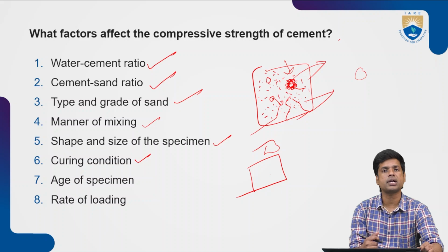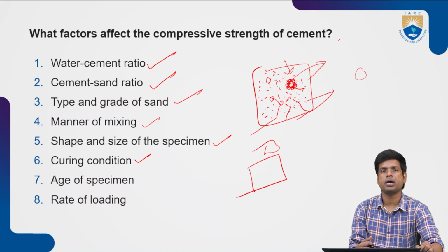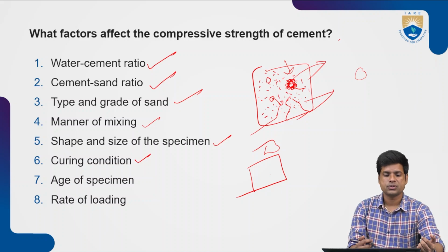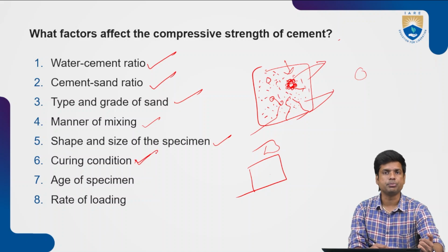Suppose the curing is not done, and the water application is missed for a few days, then what will happen? The moisture needed for completing the hydration process will not be there. If the hydration process is not completed, then the strength will be reduced. So curing also plays a major role in strength improvement.